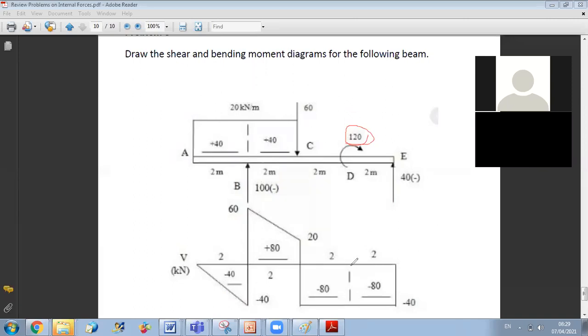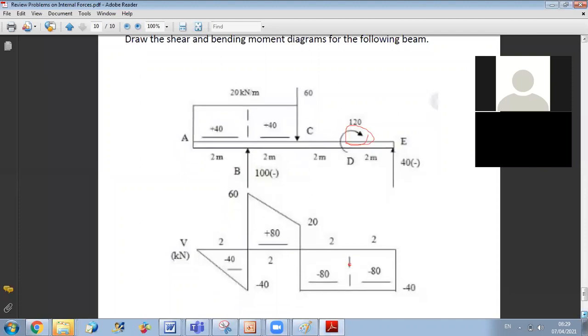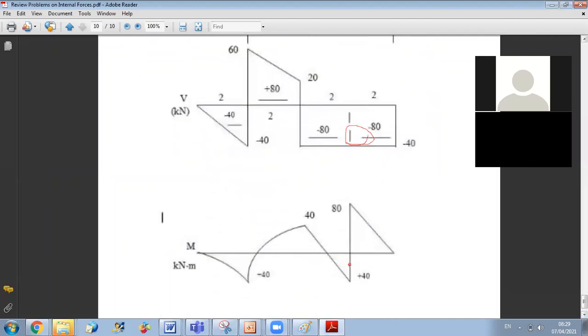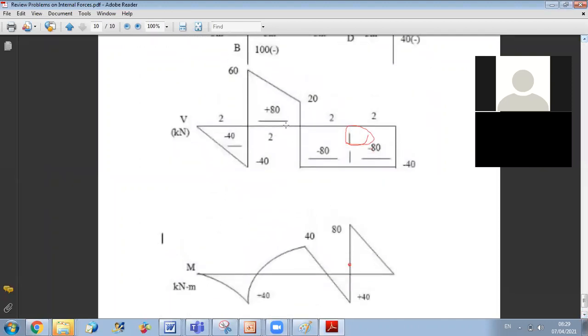So remember here to do a positive jump for the bending moment. So now I will deduce the bending moment from the shear diagram. As I told you, no fixity or couples at the extremities. This is why I will start from 0. And to verify, I should end also by 0.